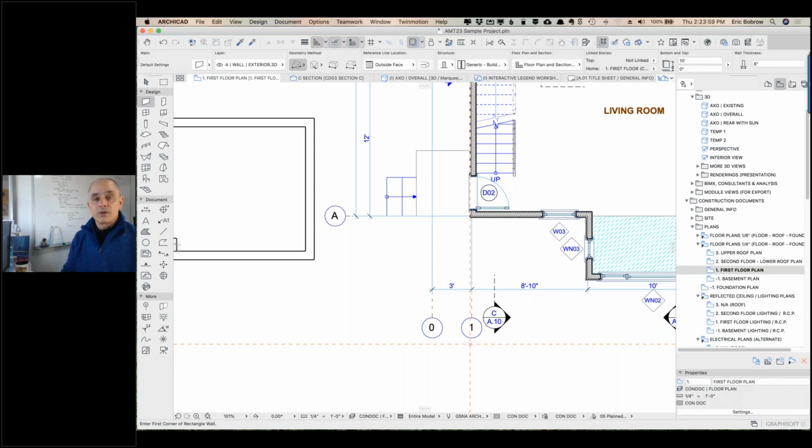Same thing for a detail drawing. It's frequently the case that when you create a detail, everything that you draw should be seen when you place it on the sheet, and you never want to turn off any of the things because you'd have an incomplete detail. So you could put everything in that context on the ARCHICAD layer, but you lose some flexibility if you wanted to, for example, work on a detail and turn off the text, because you just want to work on the geometry. Yeah, so a worksheet with a legend, simple cases like that.